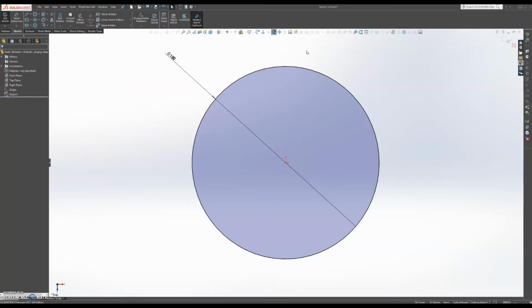And then let's say that we're going to create a gear. There are already made gears that you can choose in the toolbox, but let's say you want to create your own. So let's sketch a construction line. Snap to the center or bring it up here or here, doesn't really matter as long as this highlight comes up for you so it shows you that you are on the center.